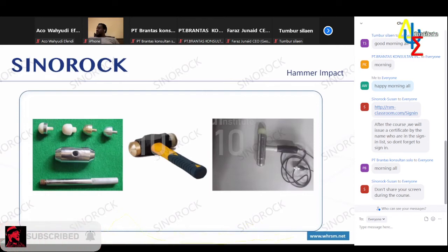It can't be very big, because its main purpose is to measure the defects of the shallow part of the pile. So it's not necessary to use a big hammer to test, mainly for the transient response method test of the dual-channel low-strain instrument.